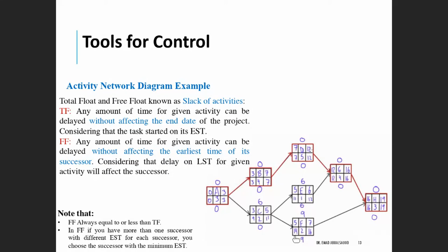So for both of those activities, the start time will be affected. And now it depends on how they have total float and free float in dealing with that delay. So these are very important values to help you manage your tasks, manage the delay in some tasks, and be strict in finishing other tasks on time so you can stick to the overall project duration. There are also some notes that I highlighted here in the corner of the page.